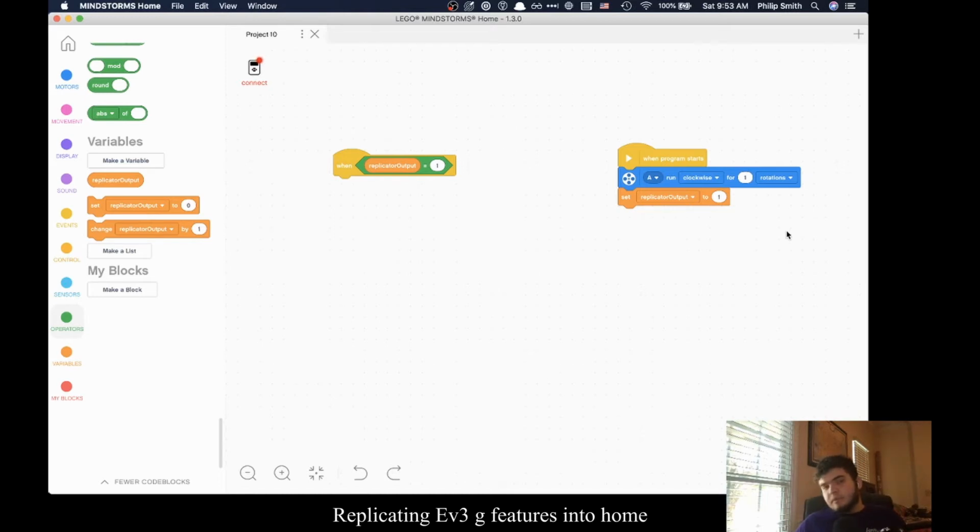Instead, you should be using it when you want to do things like, oh, if I push a button, then I want to kill my current running program so that I can take it back to base without harming itself. That's a valid use case for a thread. Or something along the lines of, if my gyro drifts more than X amount, then I want to disable gyro use in my gyro straights and turn them into just normal straights. And then refuse to leave base until it's been calibrated again. That's a great use for a thread. Kind of a complicated use case, but a great use for it.